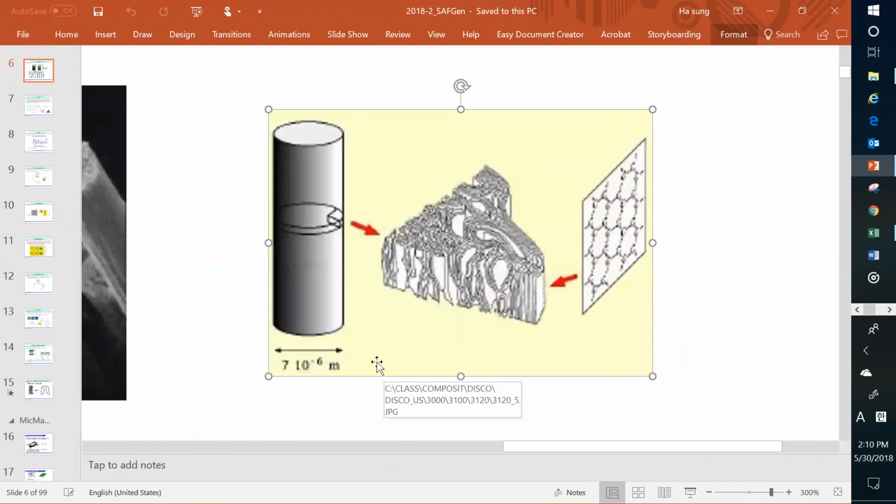This is a carbon fiber, and in carbon fibers, all the carbon atom arrays are hexagonal. This way is very strong, like a CNT, carbon nanotube, or graphene. And carbon fiber is just layers, and all the arrangement in the longitudinal fiber direction is aligned this way. So as you can see here, the transverse direction is much weaker than the longitudinal direction.